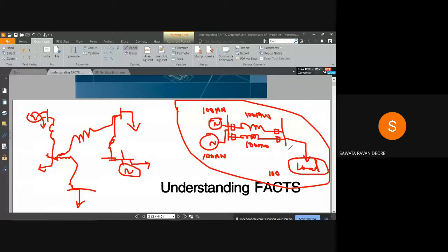So in every district, if you go, there are villages with a population of 10,000 plus or around 20,000, and to those villages there is a 33 kV by 11 kV substation. Through those 11 kV lines, 3, 4, 5 villages around that somewhat bigger village are radially connected.